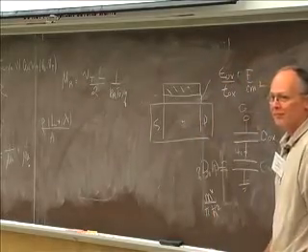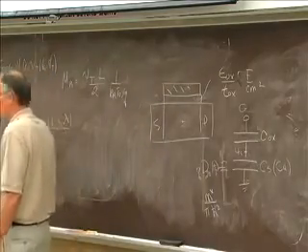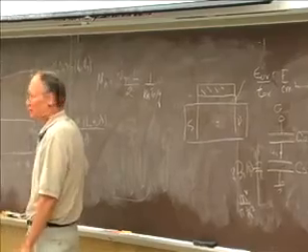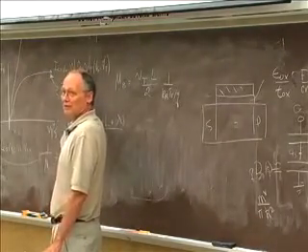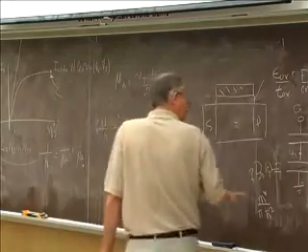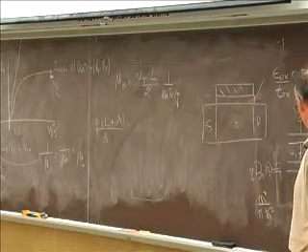So in III-Vs, the light effective mass that's giving you the high mobility might not be so important because your ballistic mobility is going to limit you, but it's also giving you the high thermal velocity, which is important because it gives you a higher drive current, which you want. It's also giving you a lower density of states capacitance.